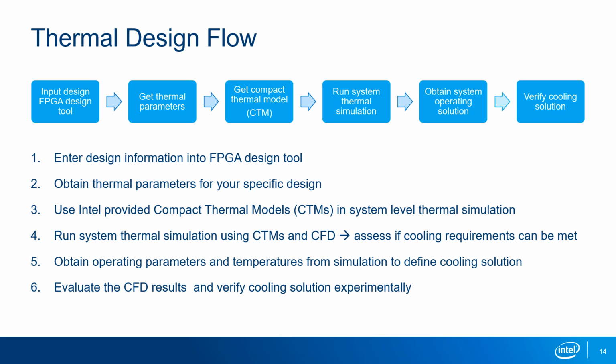The compact thermal model is a FloTHERM plugin, so you basically take the compact thermal model and plug it into the software. Once the simulation is complete, you'll have the operating parameters and temperatures, which will allow you to define the cooling solution, which we'll talk about in the next couple of slides. And then lastly, you'll need to verify the cooling solution.